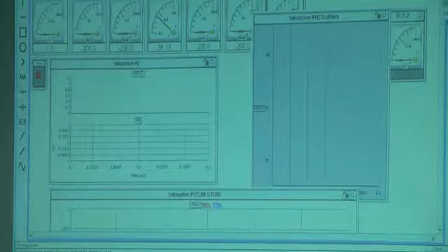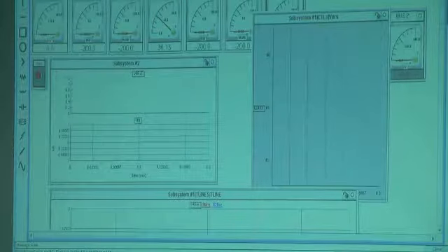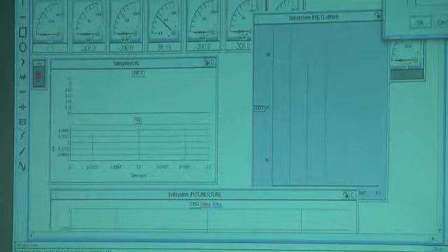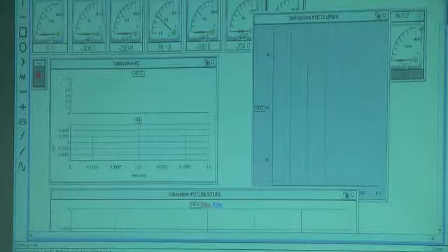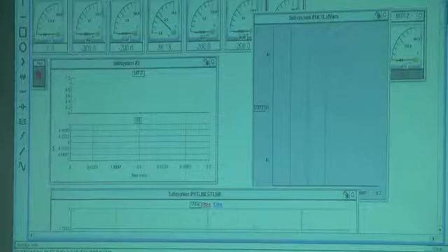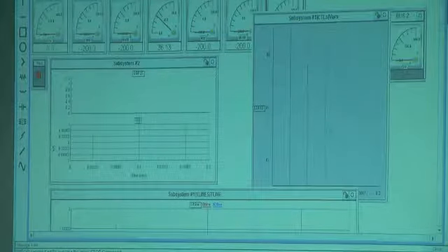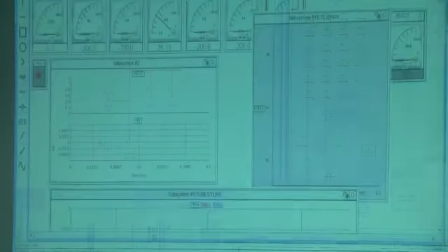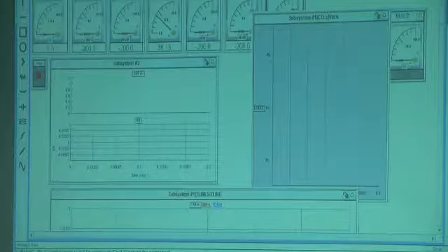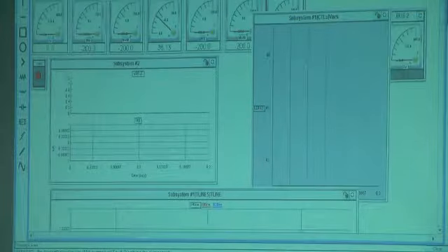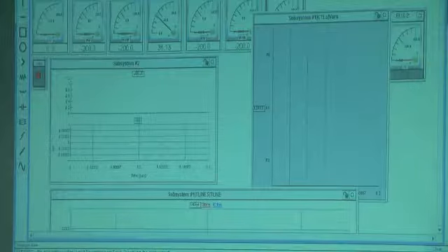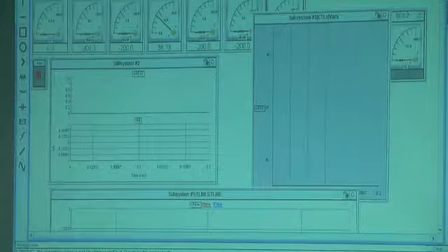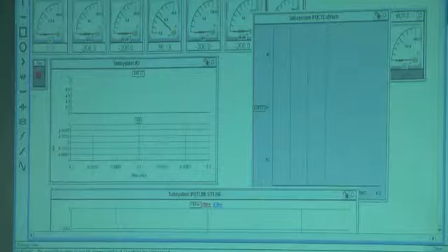Does everyone remember how to unlock the rack? Right click, unlock rack, default password is RTDS. But if someone else is running a simulation, don't stop it on them. It's not very nice. There's a reset button on the bottom. If you're having problems, just hit that.